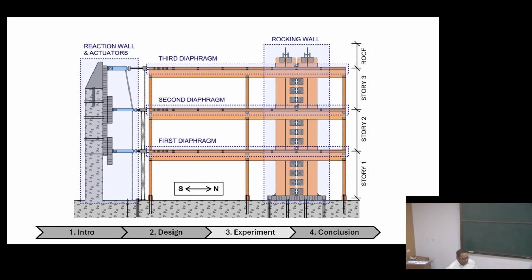This is what the building looks like in elevation. So you have your columns, which were also timber, your floor diaphragms, which were also a similar product, but larger dimensions. And this was the wall system that was installed. 3-story tall building. The post-tensioning cable rested on a saddle. You use hollow jacks to post-tension.